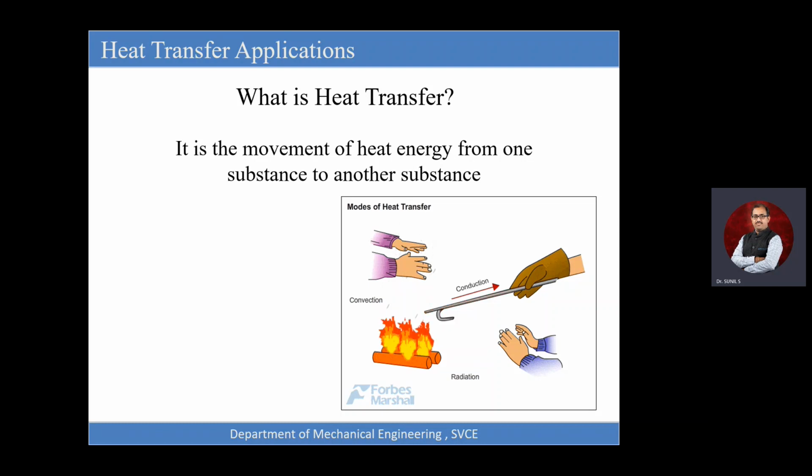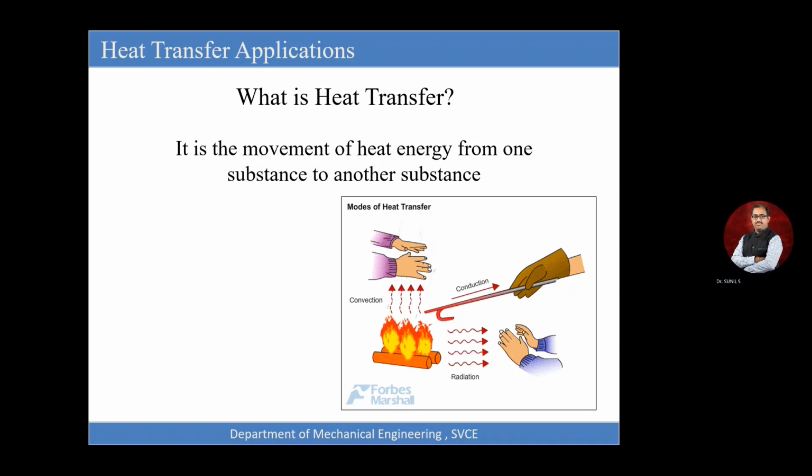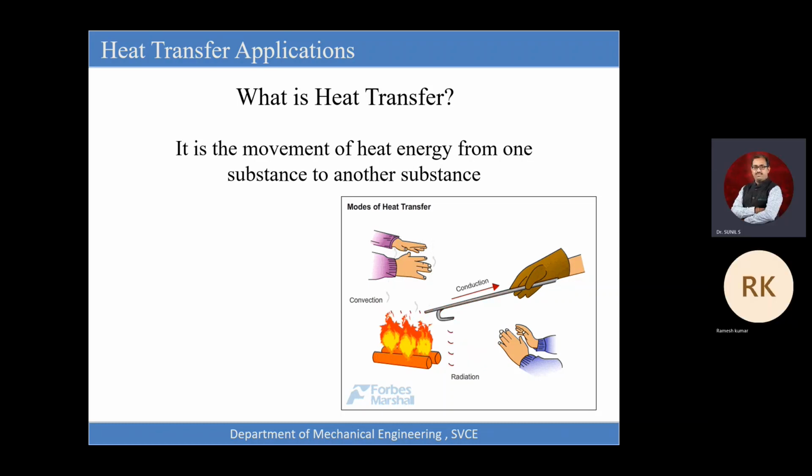What is happening in the first case? We call it as natural convection. The top layer of coffee comes in contact with air. Yes or no? So air picks up the heat. Once it picks up the heat, the density of air drops. Because of buoyancy effect, the air tries to float up. The fresh air again comes into picture. Yes or no? Over a period of time, convection current forms so that your coffee gets cooled. It will take a lot of time to happen naturally.